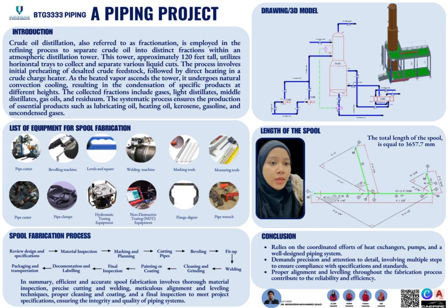So proceed with pipe 3. It involves the elbow, equal tee, flange, also the gasket, and the root gap is the same, which is 8 mm because it has two joints on pipe 3. So the total length of pipe 3 is equal to 408.1 mm.